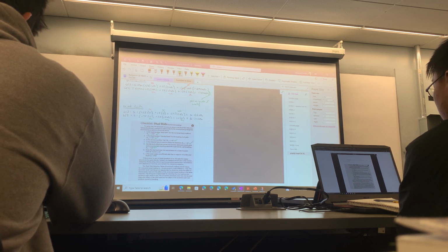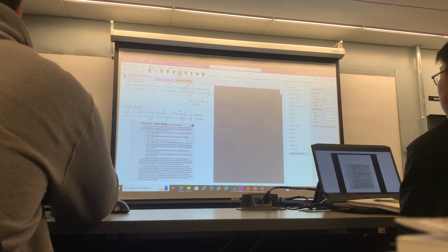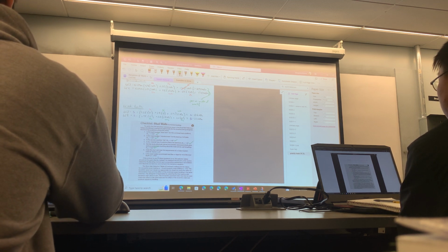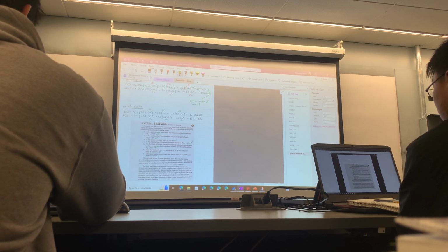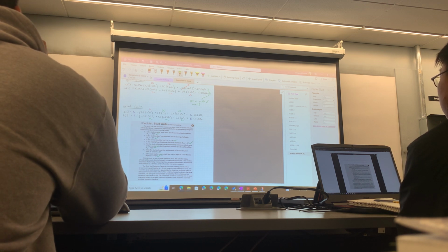Remember our failure modes: do we have sufficient nails, or did we add clips if the nails were insufficient? Is the stud eccentrically loaded, with eccentricity less than or equal to 1/6 of the stud depth? We talked about eccentric loading versus concentric. We're going to assume it's concentric loading, but you'll see it's very simple to take a more conservative approach as eccentric.